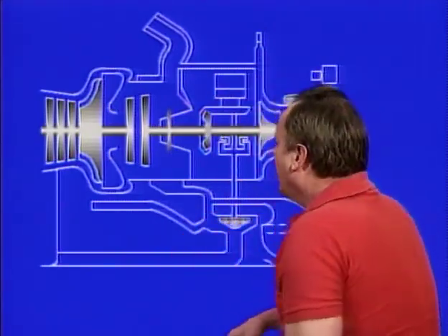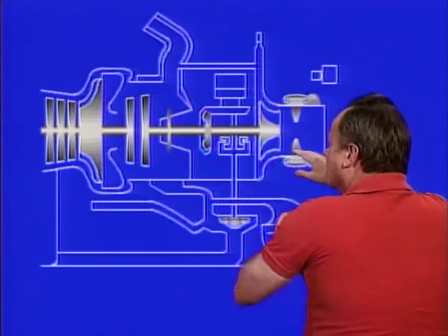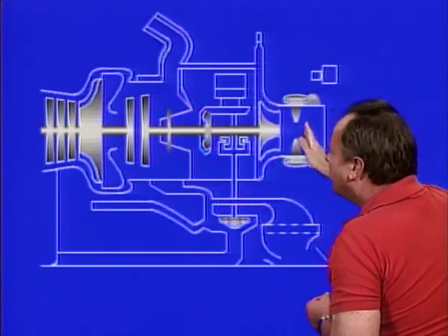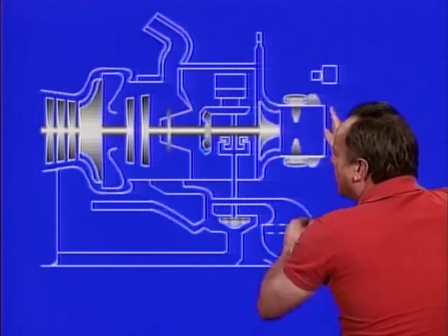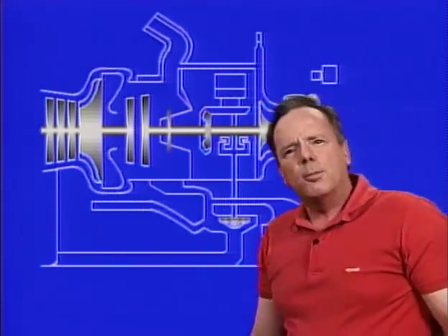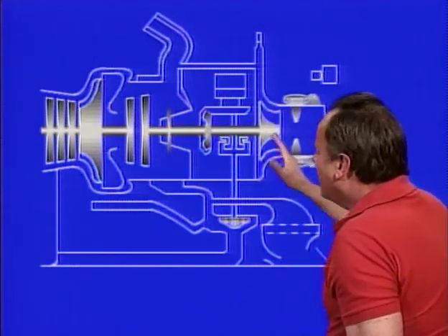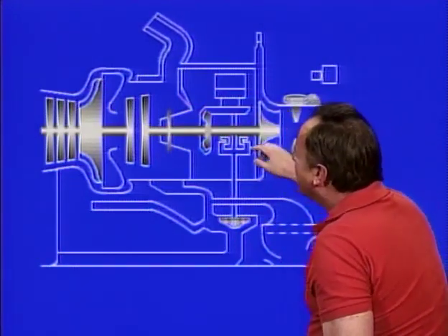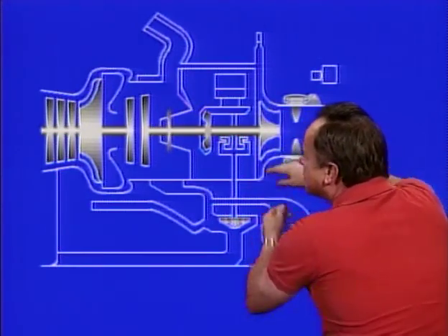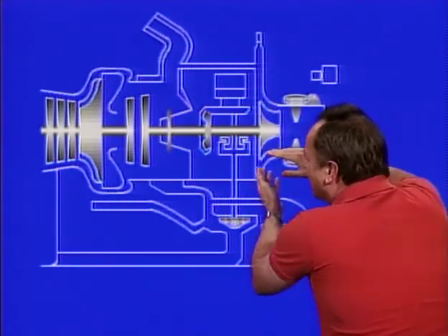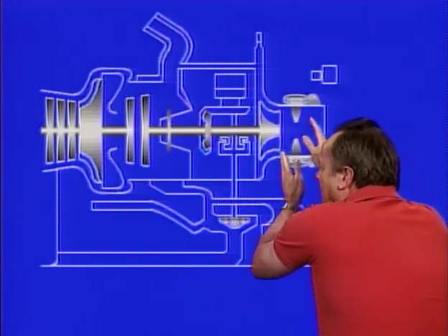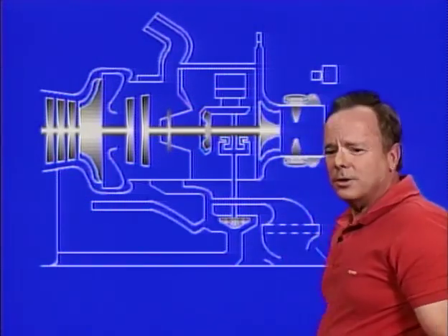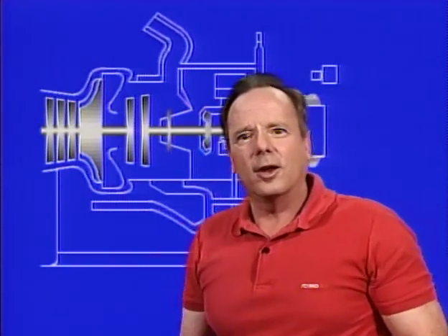Let's assume you have a change in the electrical load. How can you regulate the pneumatic load? Well, they do that with inlet guide vanes to the load compressor, and you can change the amount of air that gets to the compressor. Now, you might think, wait a minute, if you have less air getting to the compressor, wouldn't that put more load on the compressor? And the answer is no, it'd put less load on the compressor. If you change these guide vanes so that less air gets to the compressor, there'll be less load on it. That's how you regulate the air getting into the compressor.